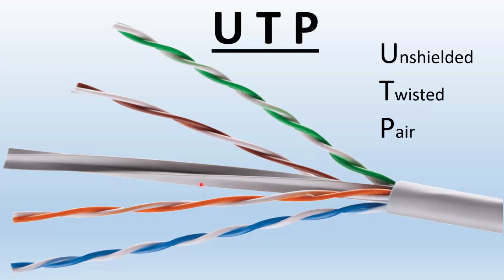So I'm not worrying as much about making those wires nice and neat, not to cause the interference. For me, it's more important that those cables in the bundle do not physically cross each other and not causing the microbends.